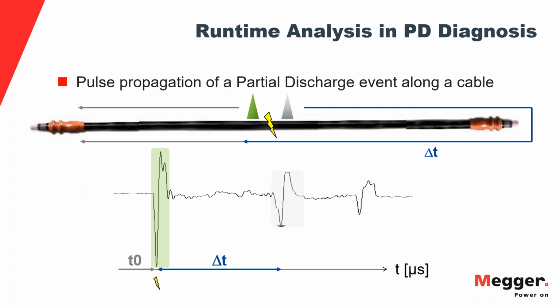And then the conventional testing is based on the so-called traveling wave approach, which is very similar to a TDR. It's in the time domain. The traces look very similar to a TDR, but pitfall, they are not identical to a typical TDR trace when you hook up a radar and then you take a measurement in the cable.